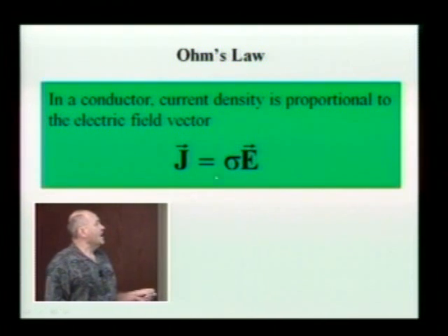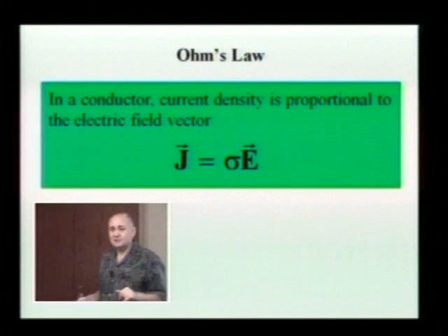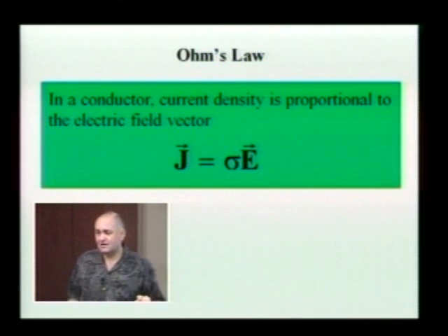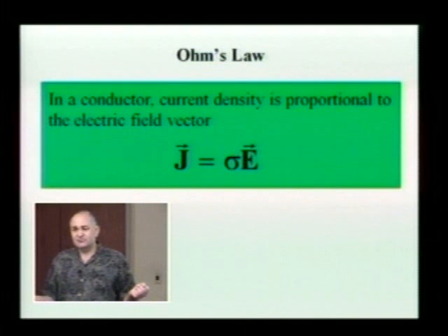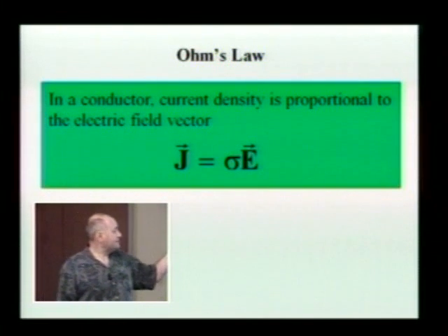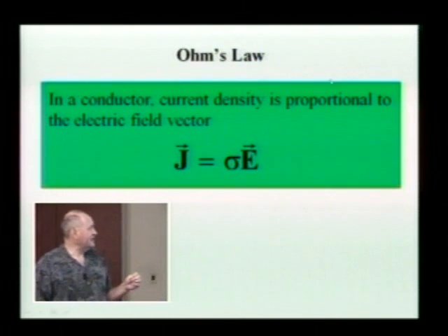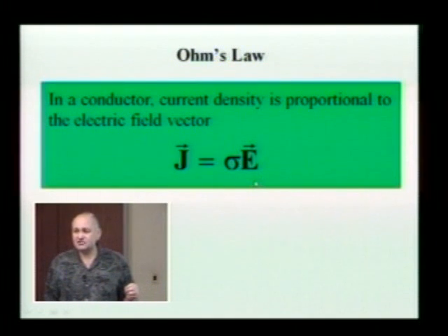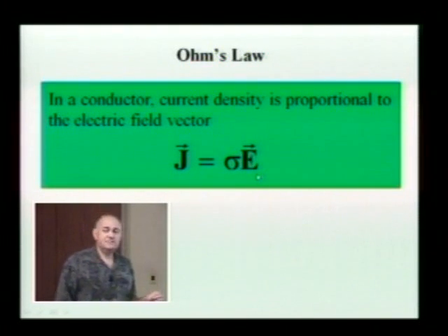This is not well, and the law which relates actually the current as the phenomenon with the external interaction is referred to as Ohm's law. And well, we have various versions of this Ohm's law. Now it's almost the most modern version, which relates current density at a particular location with electric field at the same location. And it says that current density is proportional to electric field vector.